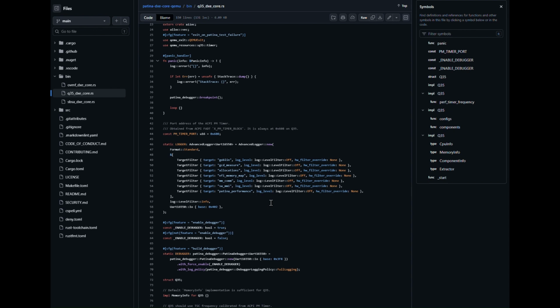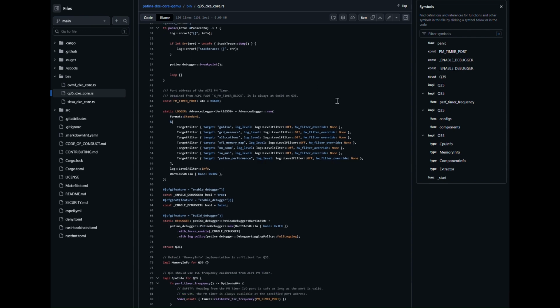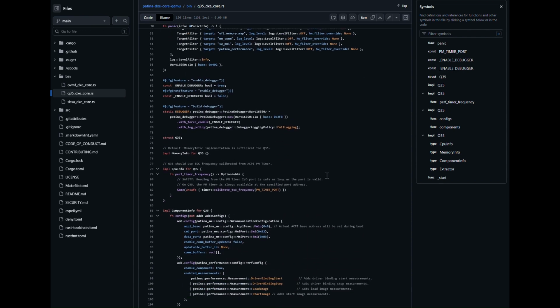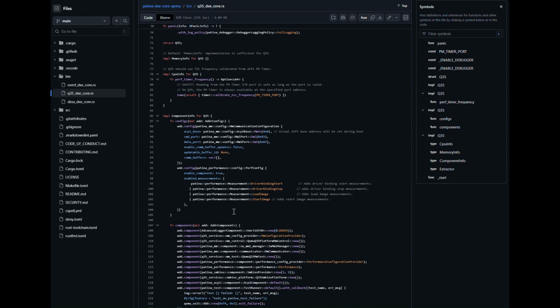So some of the details that are platform specific are, for a virtual platform, for example, how do we exit that platform? We have a crate here called QEMU exit we use in order to perform that action. We also fill in some of the details like what the UART looks like for this platform. It's a UART 16550 IO based using a base port of 0x3F8 and other details, right?